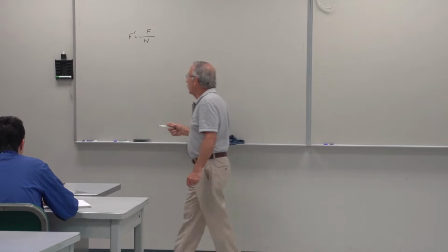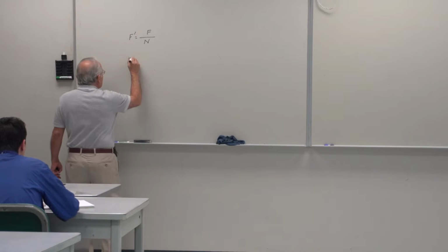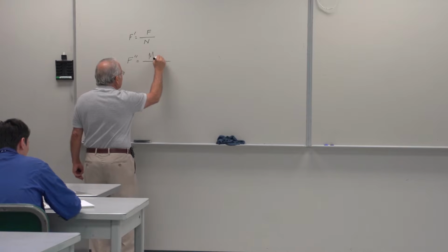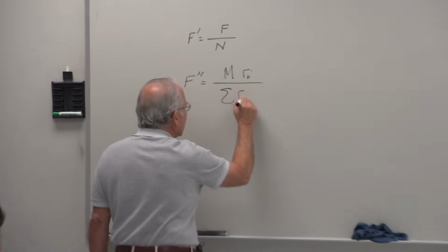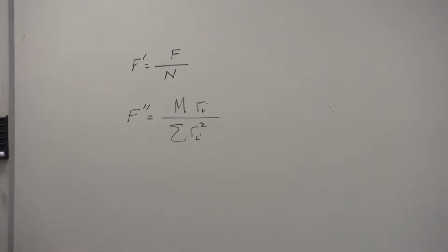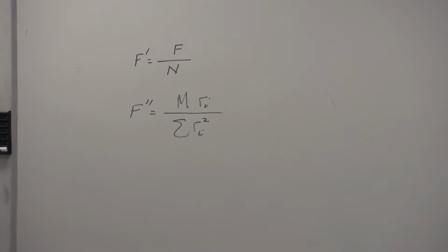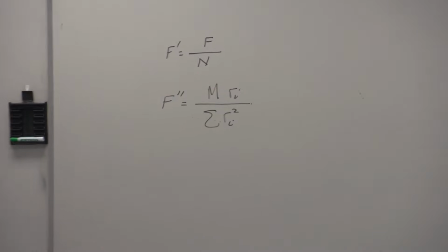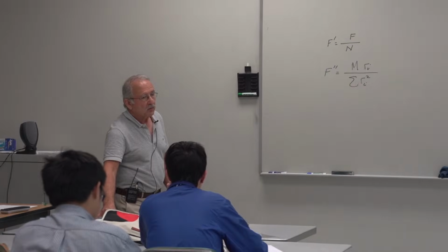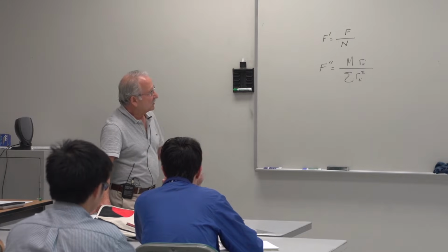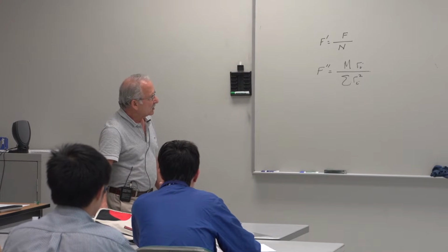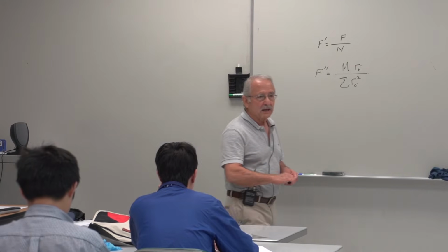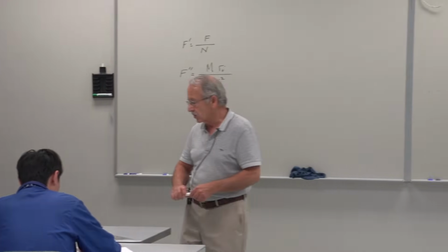However, if there is a bending moment, then we get a secondary load called F double prime, which we found out last time to be related to the moment like that. And we said that the farther the bolt or the rivet is from the centroid, and this is all about the centroid, the larger the secondary force that it carries from the application of the moment.